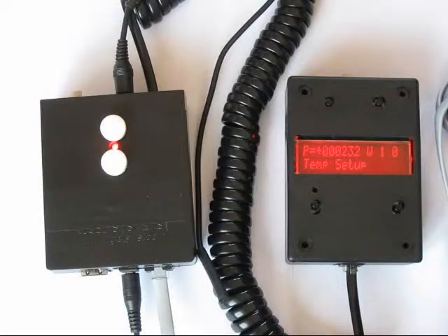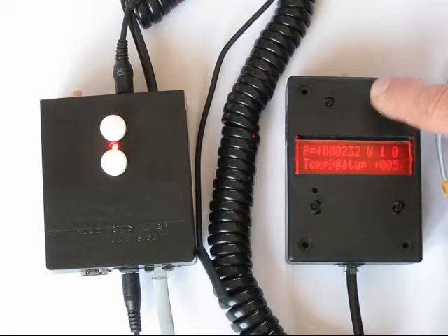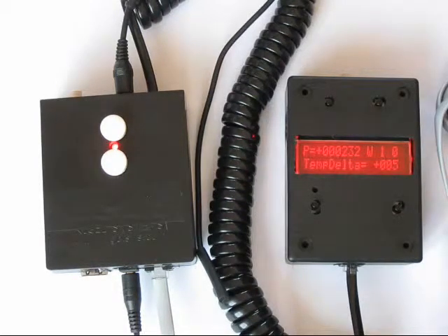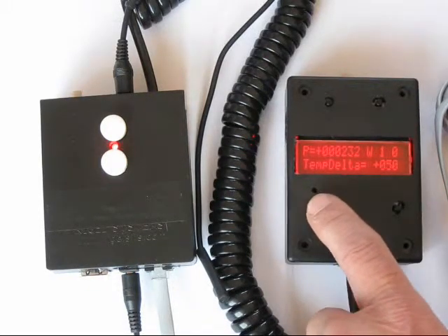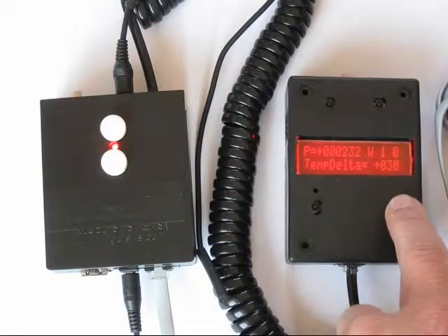Okay, so now this provides internal temperature compensation, so you can configure it to move in and out based upon a delta C change, n number of steps, and also account for backlash compensation. If we look at the submenus under here, this is the temp delta. This is a fixed point, so 005 is actually 00.5 degrees C. You can go up to plus 10 C or to minus 10 C.